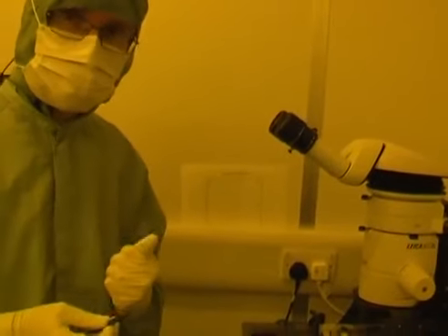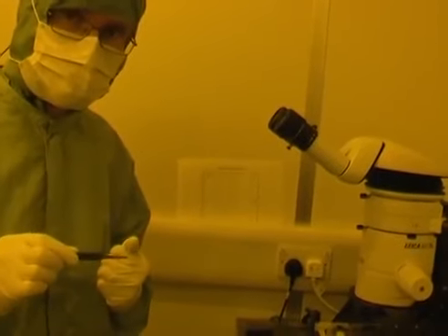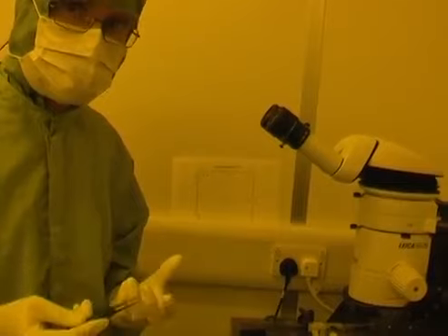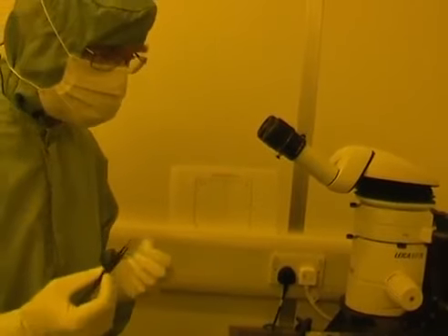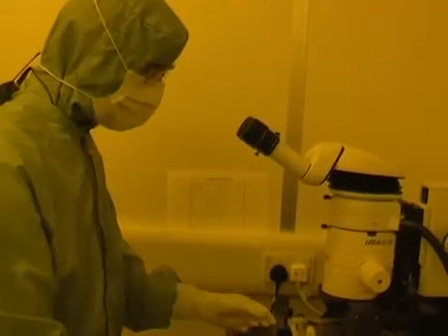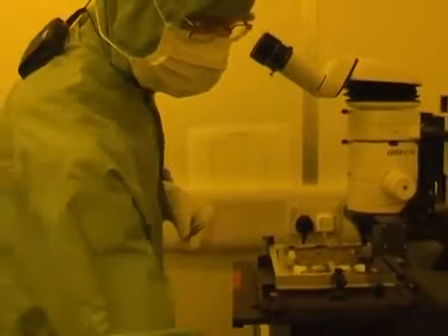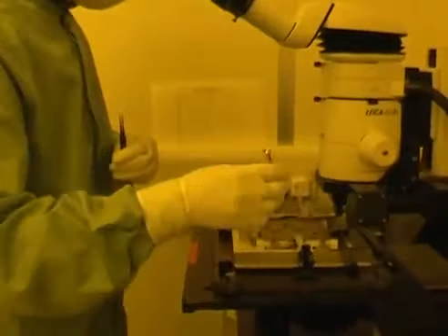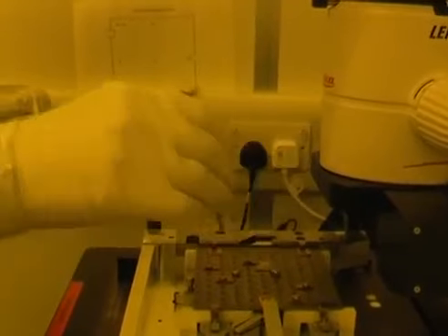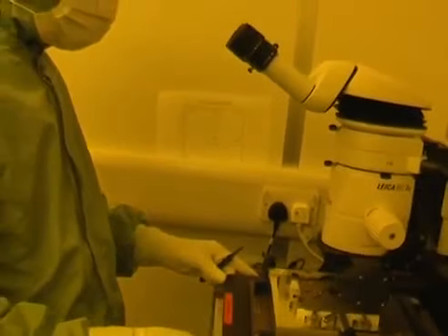If you've got a single clamp, it rotates easily about that clamp. If you've got two clamps, it won't rotate at all. So you have to loosen one of them off to do the alignment and then tighten it up afterwards. So I'm going to do that just now. I'm going to loosen up this clamp completely, otherwise I won't be able to rotate it. And then after we've got the rotation correct, I will re-clamp that particular one.